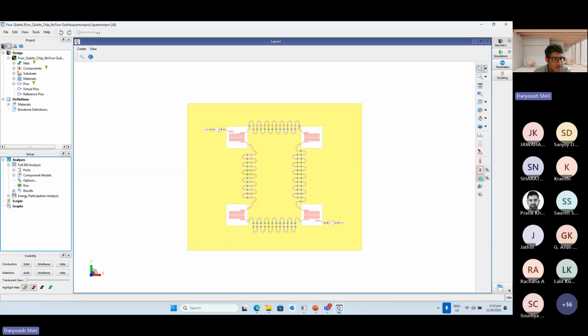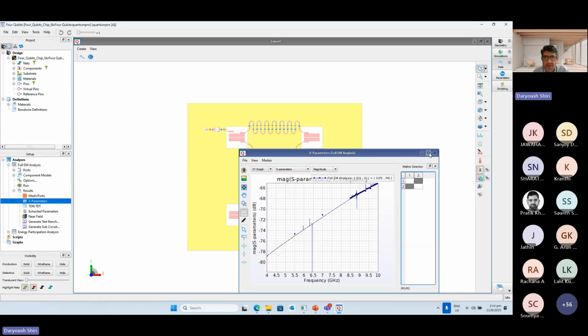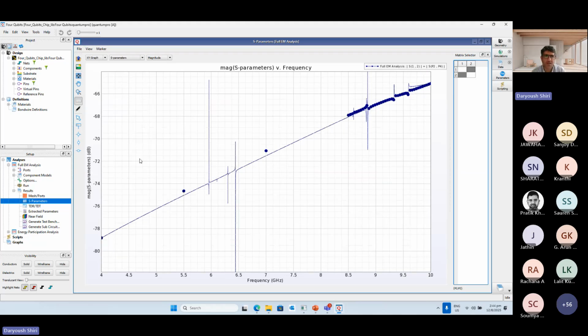So the results are there after it took like half an hour or something to get that done, because I have 16 gigabit RAM. So after mesh, you get, of course, S parameter is finished. After S parameter is done, then I just go to view, look at like better resolution, 10,000 point. You will see how the algorithm found those resonance peaks.